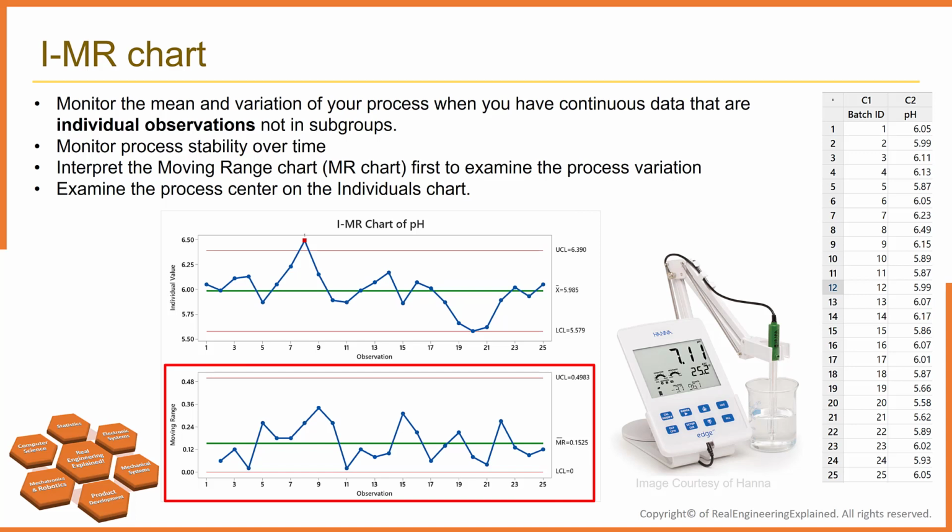As we can see, none of the points are outside the control limits, and the points display a random pattern. The points vary randomly around the center line and are within the control limits. No trends or patterns are present.